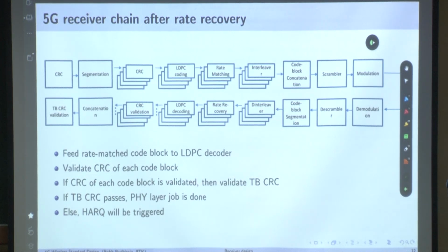The receiver has gotten the data. You have gotten your video, you have gotten your voice. If not, if it is voice, hybrid ARQ doesn't kick in. You will ask the transmitter to transmit it again manually. Otherwise, for data, hybrid ARQ kicks in, and then the same process happens.